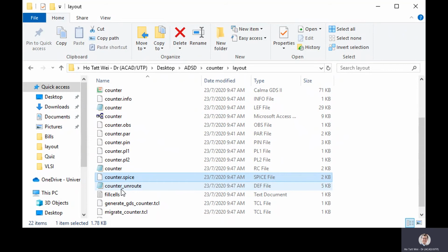So having these SPICE files could be useful if you wanted to test up-down transitions of your design, just to ensure that the transitions actually meet what you think they are doing, in terms of their propagation timing, their switching timing, and so on.